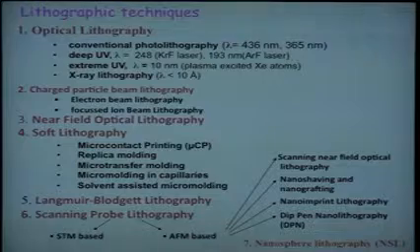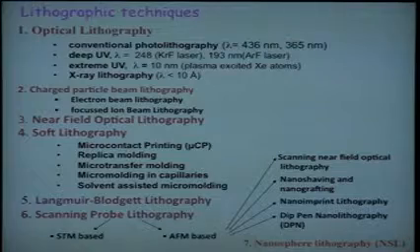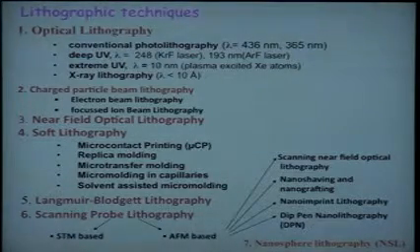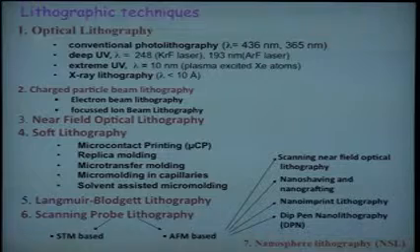So these are very specialty techniques, and in fact literature is filled with such specialty techniques. Today is not the time to get into details. Scanning probe lithography is divided into STM based and AFM based. You know the techniques, right? So an STM tip, a metal tip itself, can be carrying an electric potential, and it can cause some chemical changes on the substrate.